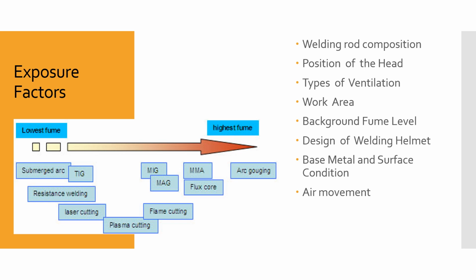Base metal and surface conditions: what are you welding on? Is it a cadmium coated or galvanized material, or paint or rust or whatever? These are going to affect your exposure. Air movement, once again, gets back to how much air is moving through where you're welding.